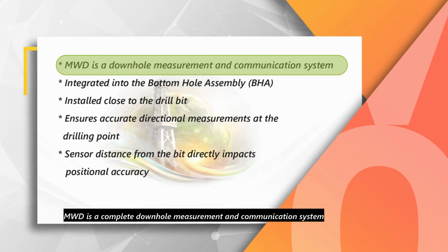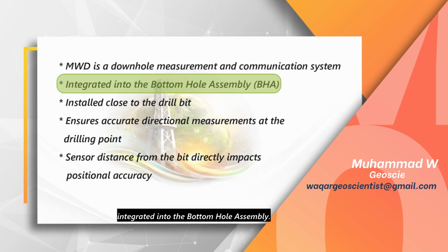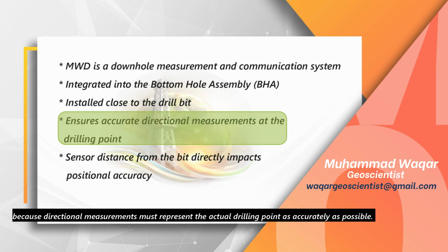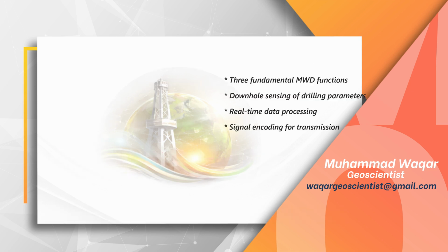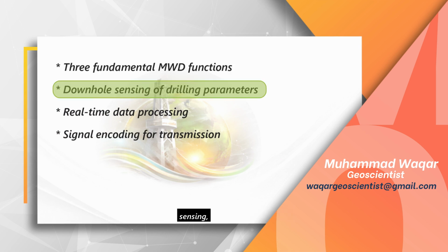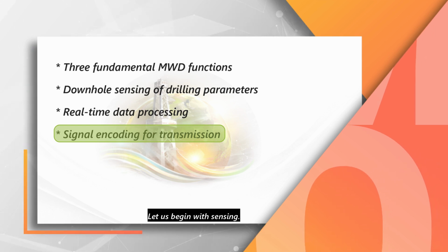MWD is a complete downhole measurement and communication system integrated into the bottom hole assembly. It is positioned close to the drill bit because directional measurements must represent the actual drilling point as accurately as possible. The further the sensor is from the bit, the larger the positional uncertainty becomes. The MWD tool performs three fundamental functions: sensing, processing, and transmitting. Let us begin with sensing.